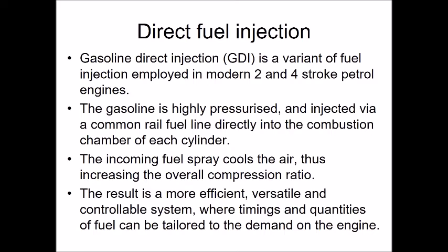So what we end up with is a more efficient engine because we're cooling the air and fuel mixture as we spray the fuel in, because the fuel needs some energy to evaporate, and it gets that energy by actually extracting heat from the air that's being squashed. So it's more versatile, more controllable, and we can start to tailor things. So we can have variable valve timings, but we can also have variable injection quantities, all clever stuff.